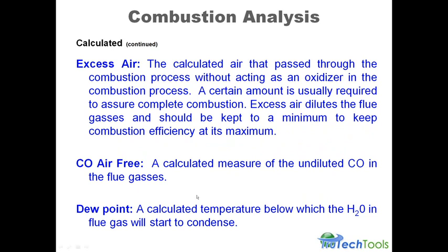The dew point is the temperature below which the water in the flue gases will start to condense, and that's again a calculation. We care about that too because if we're talking about a non-condensing appliance like an 80+ furnace, we don't want it raining inside the chimney. If we can measure the temperature of the flue gases exiting the chimney, let's say the dew point's 100 degrees, or maybe 150 degrees, and we get up to the top of a brick chimney and the flue gases are coming out at 90 degrees, we know that it's raining inside that chimney, that the flue gases have dropped below the dew point temperature, and those flue gases are going to start to condense.